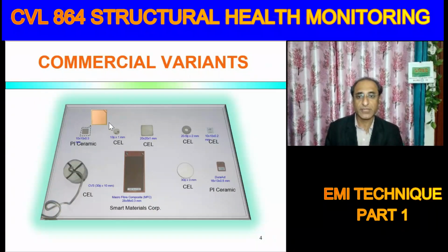For example, this circular one and this square one. This does not have this flexibility. They are like top electrode you have to bond to the top, and the bottom electrode you have to solder to the bottom. Of course, there are ways of doing that. A very thin film we have to insert below the bottom electrode, and then also we can do soldering.